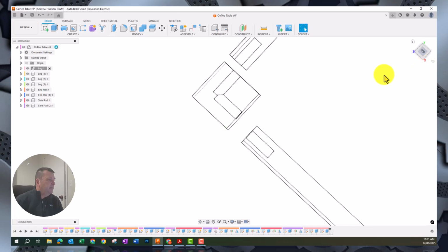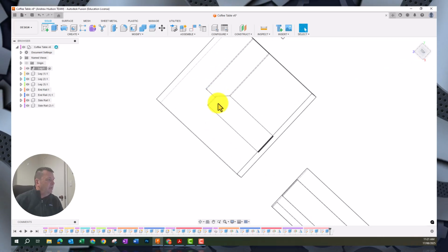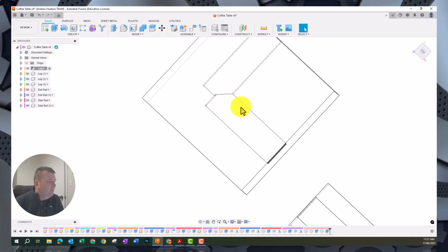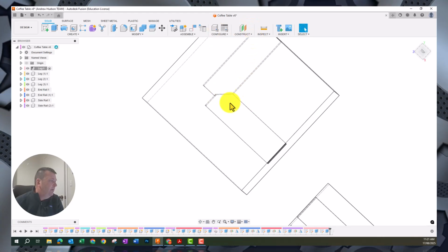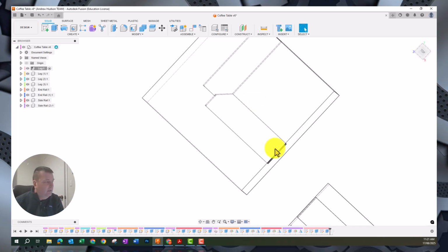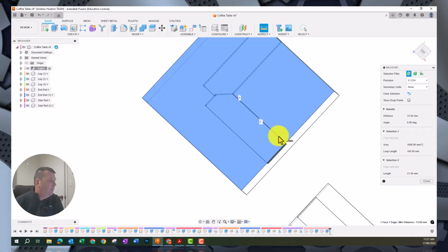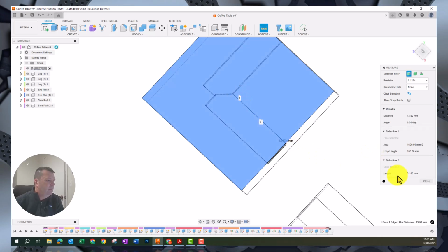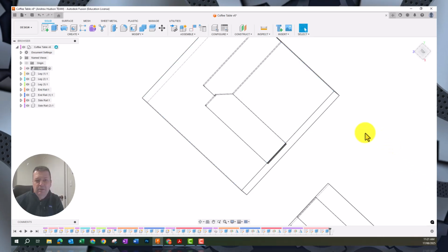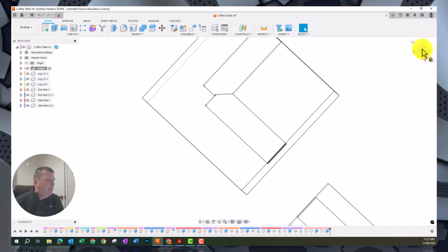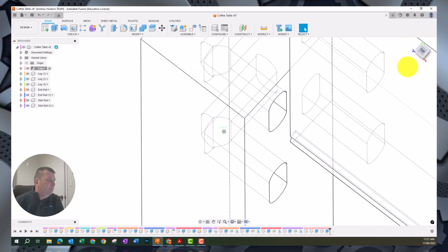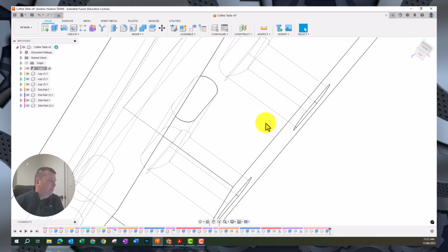Our dominoes are going to smack into each other. So you have to adjust that slightly. We are going to need to bring that back a little bit because of that, so that they may be 20 mils in here. Let's have a look, see if we can work that out. No, not really. Length, so 21. So yeah, we're going to have to make those 20 mils on one side, 30 in the other. But that's all right, that's doable. We'll fix all that up later on.